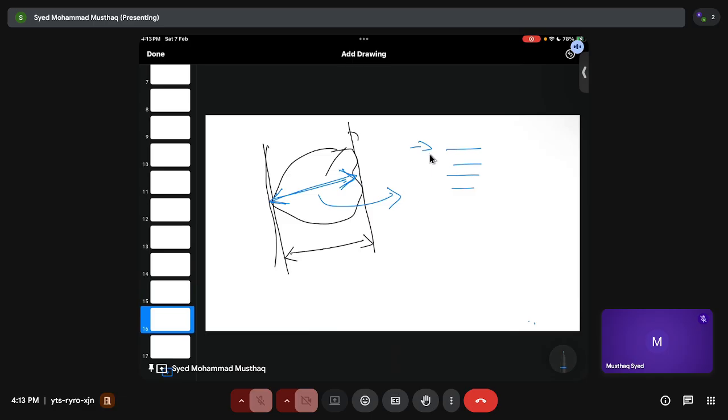Now, there are also industrial screenings, and the industrial screenings have a certain feed rate and a certain size of aperture. And there is also vibration, right? You can even have dry screening. There is also wet screening. It depends on whatever equipment you are trying to use. So what are the different things that affect this screening? The particle size, obviously, because that's what we are trying to separate, right? Then you have feed rate, the amount of feed that you are trying to give, and also the screen angle.